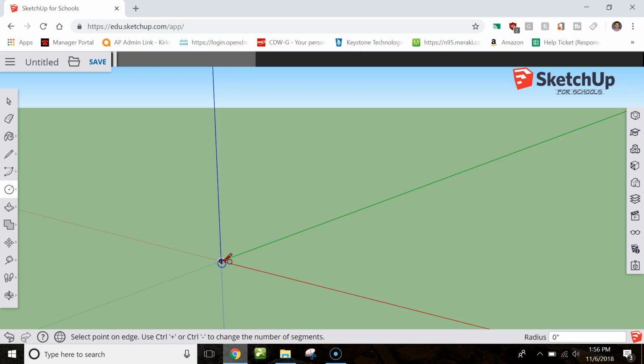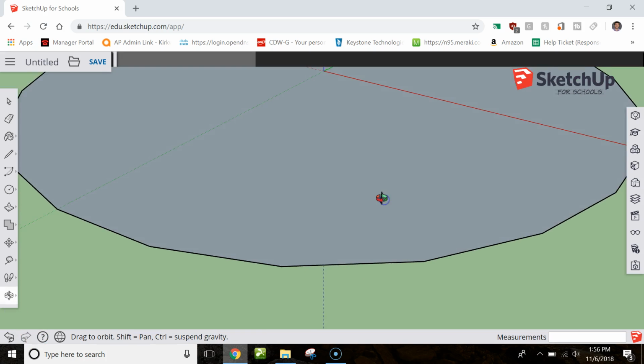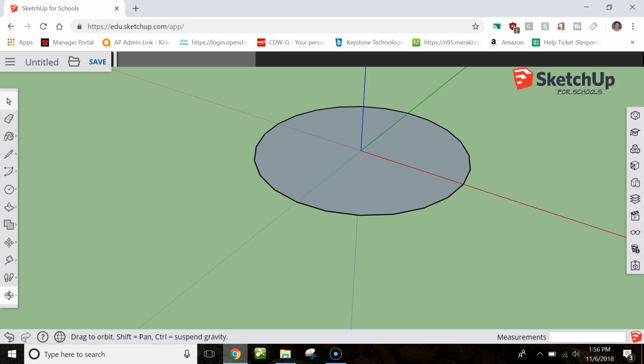Click that, go from the origin point, and we want to keep it in line with what we've been making with our other rockets, or the other portions of our rocket. So I'm going to use a 1-inch radius to make it a 2-inch rocket. Makes it tiny, so we zoom extent in, and let's zoom out a little bit. There we go.